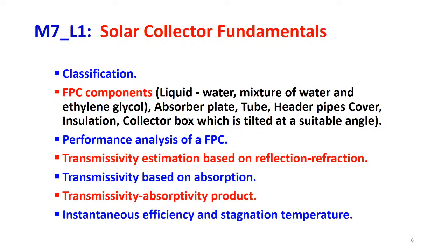Also, we have discussed the performance analysis of a flat plate collector. Transmissivity estimation based on reflections and transmissivity estimation based on absorption were discussed extensively. Also, we have learned the significance of the transmissivity-absorptivity product.